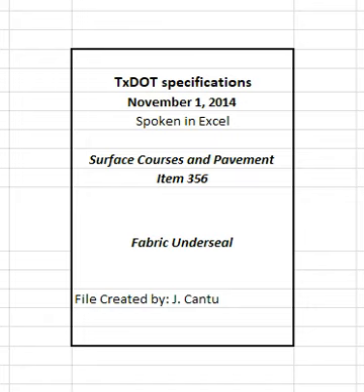3. Equipment. Provide applicable equipment in accordance with item 316, seal coat, for longitudinal, full width underseal. 4. Construction. Apply fabric underseal when the air temperature is 60 degrees Fahrenheit and above, or above 50 degrees Fahrenheit and rising. Never apply when surface temperature is below 50 degrees Fahrenheit. Do not apply when, according to the engineer, weather conditions are not suitable. Measure air temperature in the shade and away from artificial heat.